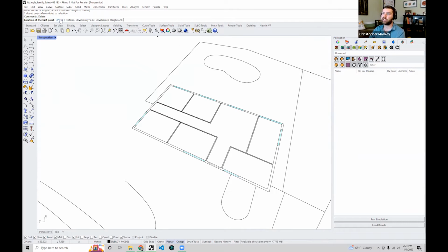This time you'll see that there are a few different options we have on this command when we draw a room. By default, it's using this 3-point one, or it's more like 2-point because we're just doing 2 corners of the room and then automatically assigning a height to that. Instead, we're going to use this freeform option here, which is going to allow us to trace whatever we want in 2D plan. That'll be much more amenable to our case here where we don't have a box that's perfectly aligned to the XY axis. You can simply left click on this little freeform button, and that's going to change the whole menu here.